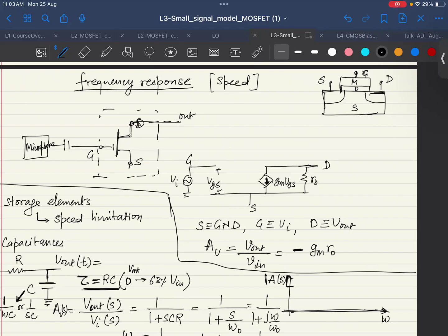And then from there, we saw that there is this VCCS formation in the saturation region, which can help us evaluate these amplifiers. Now we are asking a question: are there capacitances also hidden in my structure, which I could not see? So let's look node by node, because we have nodes in our circuit. So the question is, is there a capacitance between gate and source?